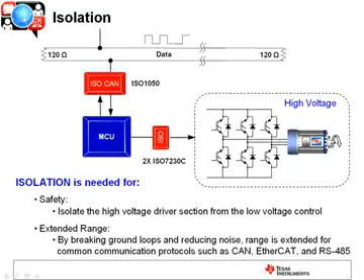TI's got some really nice devices in this area. The ISO1050 is actually an integrated CAN transceiver with isolation built in. And again, that will help extend the range, and it does that by breaking the ground loops and just reducing the noise overall.